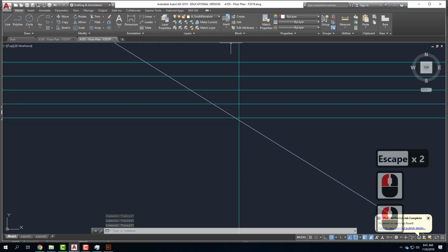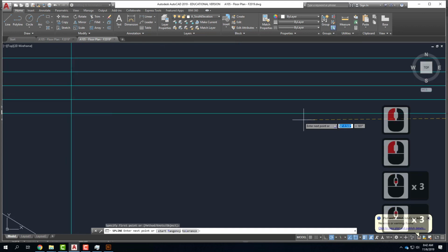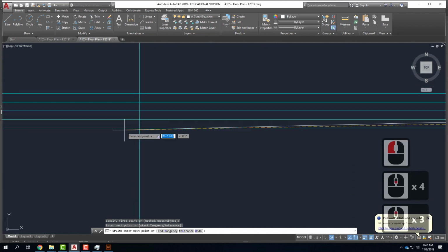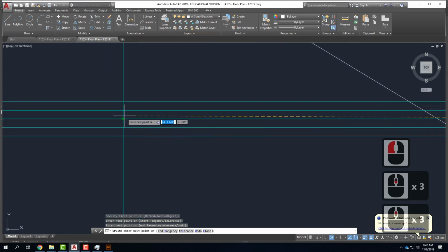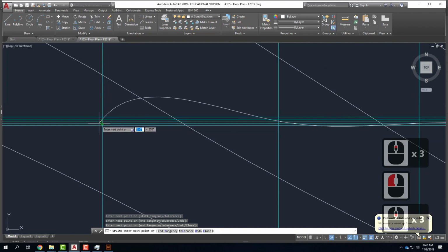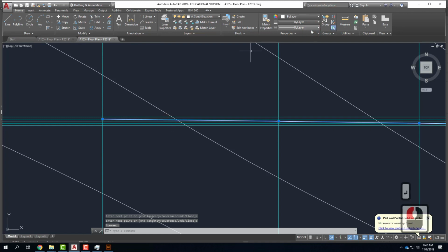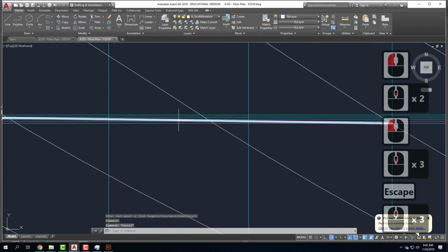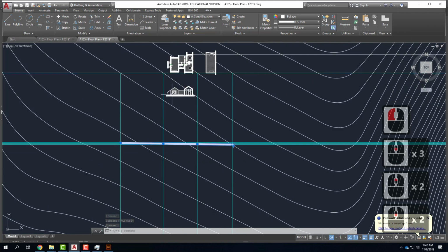south elevation layer. I'm going to go ahead and go to that spline tool right here. I'll start at my first point there. I'll move up. I'll move over to my next contour and go up by 1 foot. I'll move over to my next contour and go up by 2 feet. There it is. And I'll move to my last contour and go up by 3 feet. When I'm done, I'll press enter. And this line here, I'll make it thicker so you guys can see it, is now the slope of the terrain along the back side of my building.